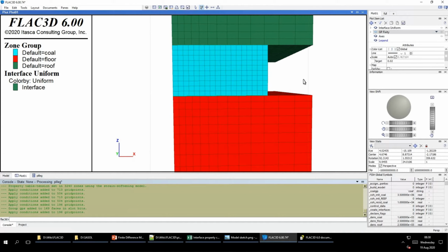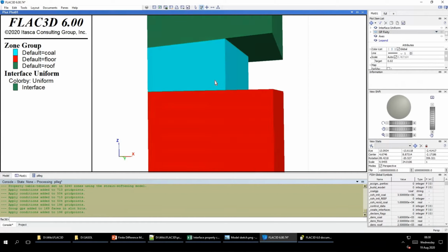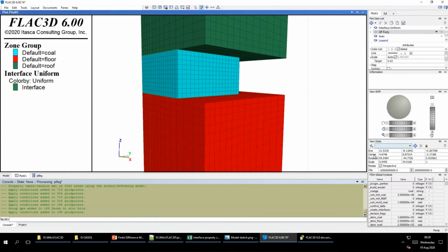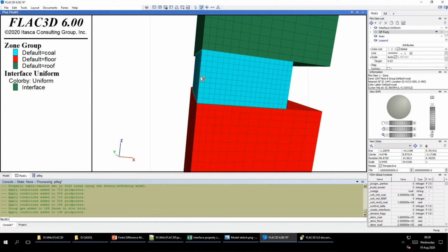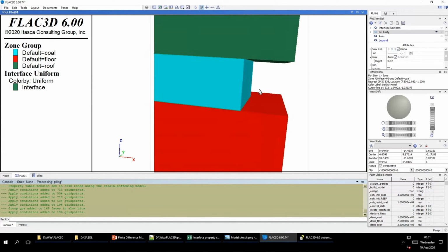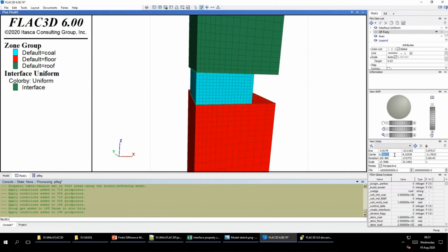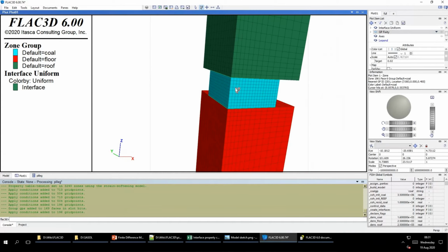Yeah, this is where I wanted to explain a bit of how to navigate in this space. So with your right mouse button, everything is done by the right mouse button. I do a rotation. And you'll see here in this little view stats window, there's a variable called center. Now that is the center about which I'm rotating. You can see I'm not rotating about 0, 0, 0, which is here. I'm rotating about a point here somewhere, which is 4, 8, minus 2. Okay. So you can change that manually very simply by just going 0, 0, 0. And now it will rotate about this line here.